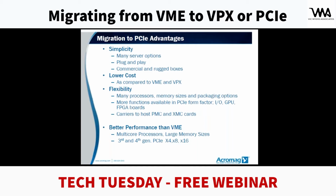Typically, you're going to get much better performance than VME, and in many cases, very similar to performance to VPX. There are multi-core processors, and we're talking about PCI Express interfaces that are very fast. First and second generation are pretty prevalent, but there are many third and fourth generation type solutions out there that offer by 4, by 8, and by 16 lane PCI Express cards.